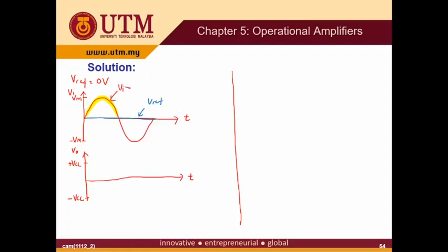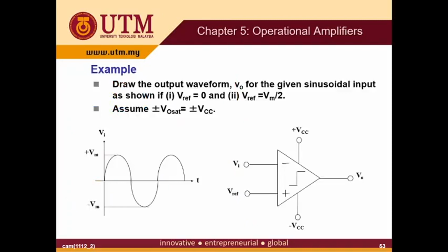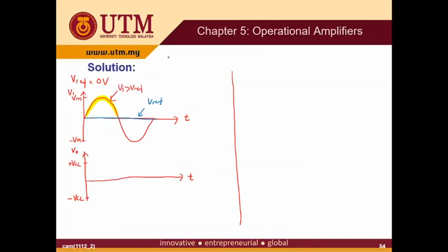You check again the circuit whether this is an inverting or non-inverting amplifier. So V in is at V minus and V reference is at V plus. Please make sure that you take note of that.